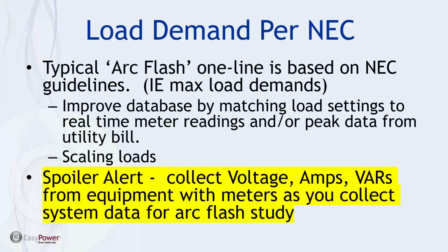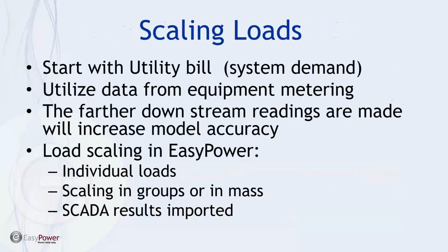Just forewarning, it's recommended that as you're doing data collection for an arc flash study, if the equipment has metering systems, it's not a bad idea to write down the volts, current, and VARs from the meters as you collect the data, whether an arc flash study includes doing the power flow study or not. So more on that later.